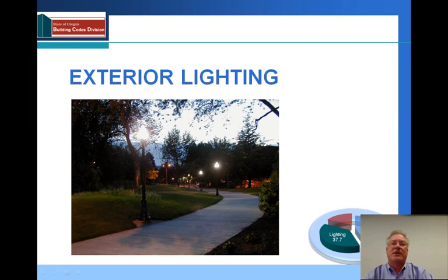We can accomplish the requirement for controls with a combination of photosensors or time switches, particularly astronomical time switch devices. An astronomical time device takes into account the changing of the seasons, daylight savings time, etc., so it knows when morning comes and when the sun falls.